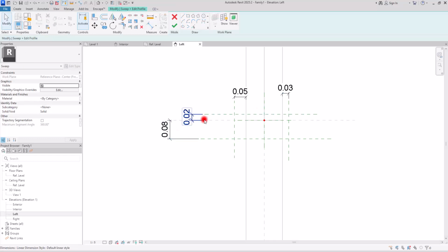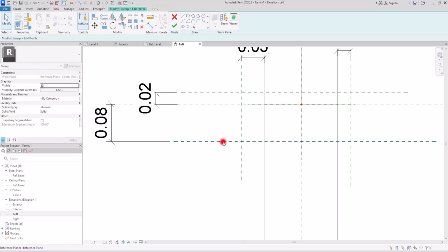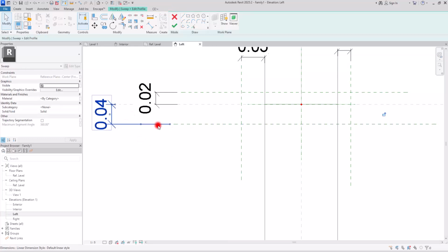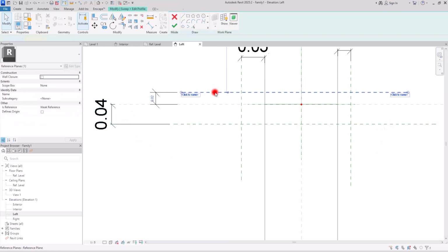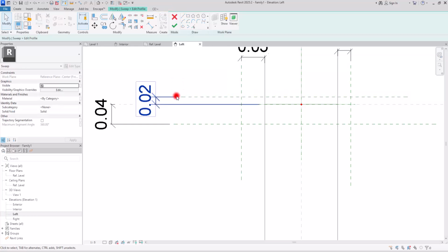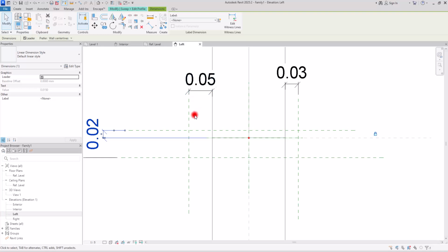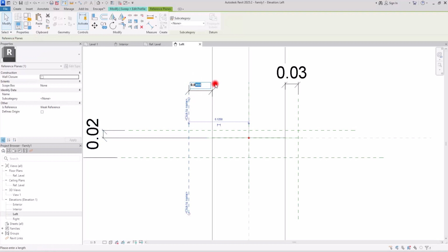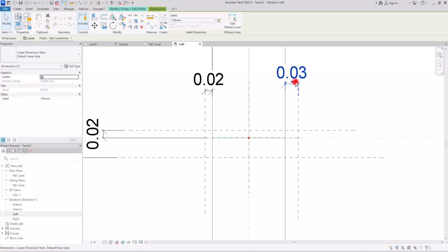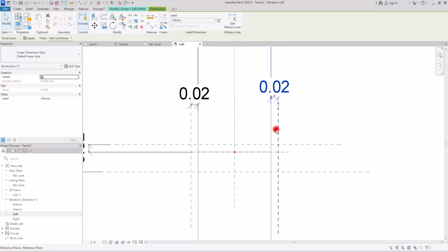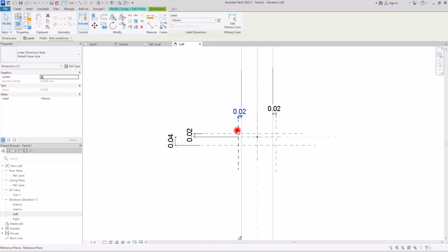Now for the size that we are going to have in here, I want this part to be something between 4 or 5 centimeters. Let's go with 4, and then I'm going to select it and lock it. For the top part, we are going to go with 15 millimeters. So I'm going to create it on 15 and then simply select the dimension and lock it. For these two parts, again, we are going to go with just 15 like this, and also for this part, and then we can lock both of them, this one and also this one.